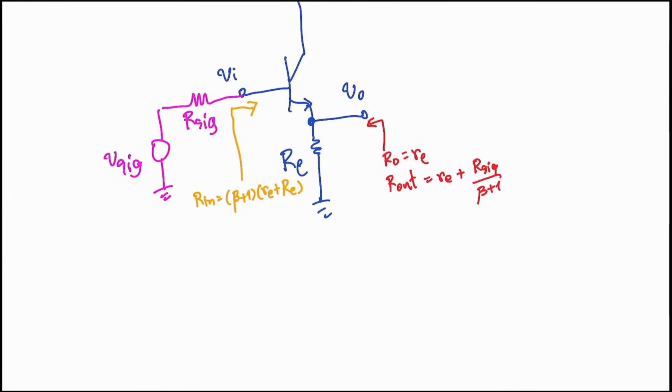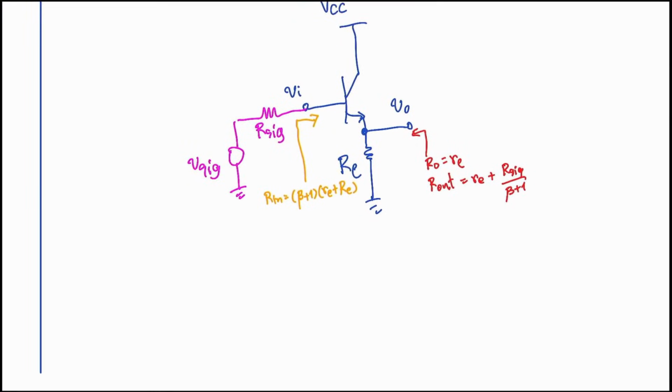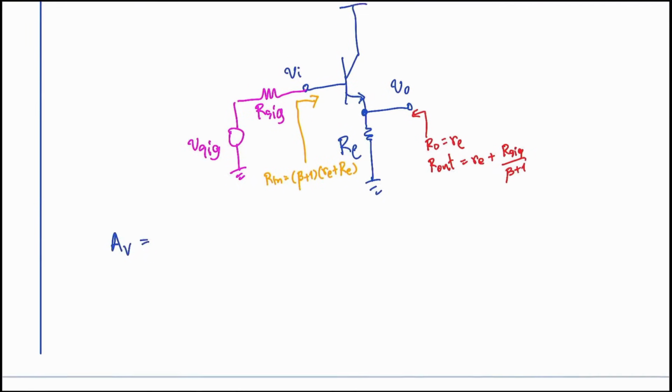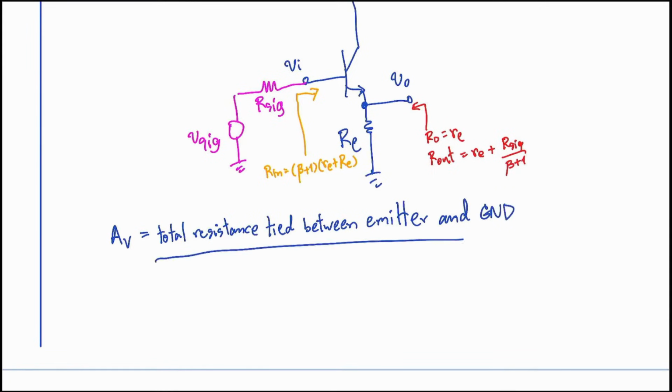I'll try to write it out as an equation to indicate the positions, okay? So this calculation ultimately leads us to a very specific conclusion regarding the gain of the circuit. Now, how should I best express this mathematically? Well, the gain is essentially equal to the total resistance that exists between the emitter terminal and the AC ground, divided by the emitter resistance, which we call Re, plus all of the other impedance factors sitting on top of that in the circuit configuration.